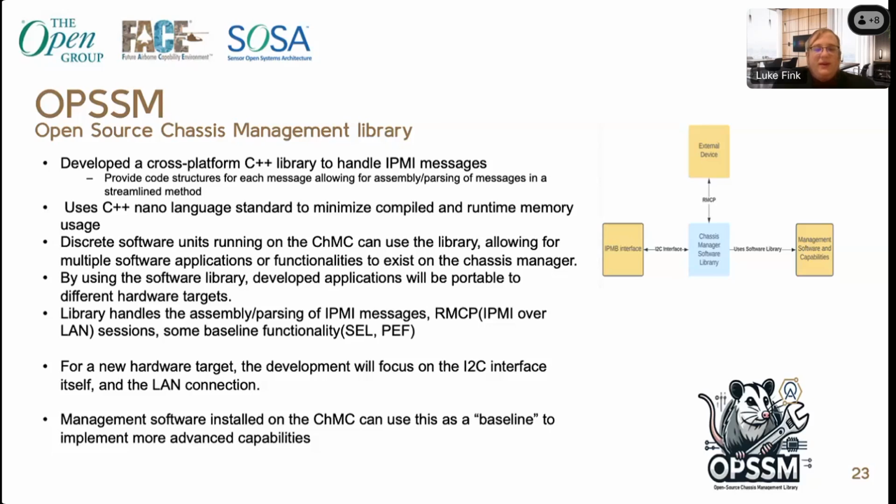So if you were to want to use this library on a new hardware target, the burden would be focusing on just getting the I2C interface to work on that hardware and the LAN interface, rather than rewriting code for managing IPMI itself. And then after that's complete, you would be able to implement advanced capabilities on top of that software.